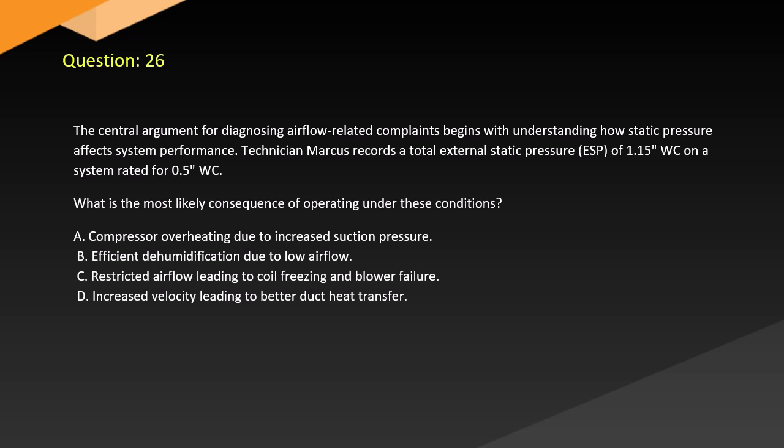Question 26. The central argument for diagnosing airflow-related complaints begins with understanding how static pressure affects system performance. Technician Marcus records a total external static pressure, ESP, of 1.15 for a system rated for 0.5. What is the most likely consequence of operating under these conditions? A. Compressor overheating due to increased suction pressure. B. Efficient dehumidification due to low airflow. C. Restricted airflow leading to coil freezing and blower failure. D. Increased velocity leading to better duct heat transfer.